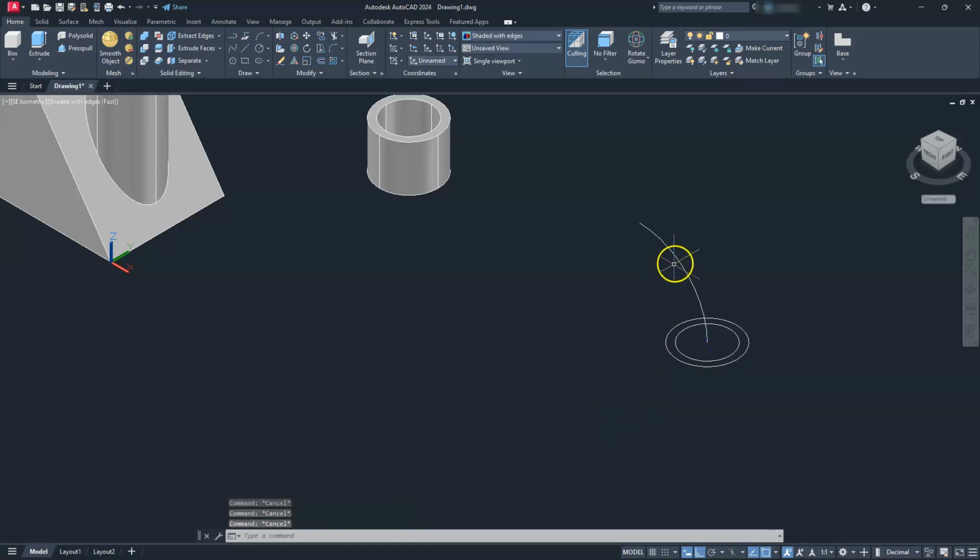Next thing I'm going to do, I'm going to go ahead and rotate this since I know that pipe is going to kind of face this way. So I'll go ahead and select this arc. I'll select the blue axis, and then I want to rotate it to when it comes towards me, like so. And let's see if I can get this to do it right. Sometimes it's kind of weird how you got to look at it. Oh, I selected the wrong axis. Sorry. Let's do that again. Select here. Select the blue axis. There we go. And I want to go that direction.